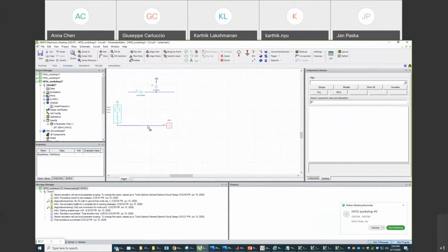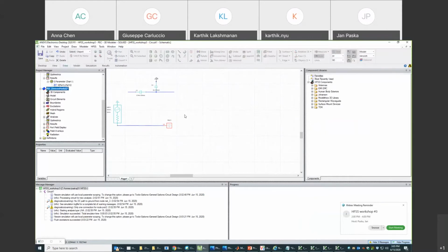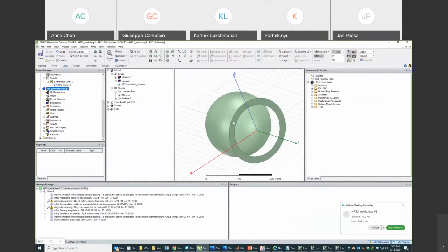You can then compute a different reflection coefficient for the 3D simulation, and update the result in the 3D simulation and change in this way the electromagnetic field. In this case, because it's only a single channel, it's going to be only a scalar, complex factor that you multiply the field globally with.